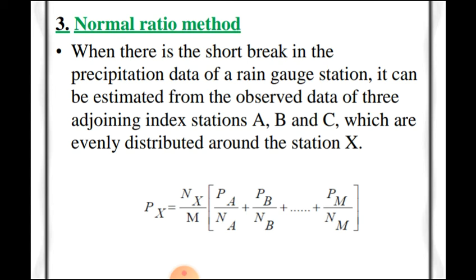Related to that, there is a concept of global maximum precipitation occurring in an area. That is probable maximum precipitation, used in extreme cases where we design something very critical, for example large dams or catastrophic cases. For that we can find out the PMP, probable maximum precipitation, which is typically written as the mean plus some factor times the standard deviation.